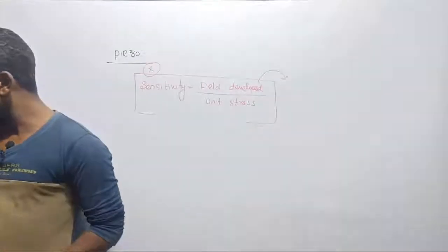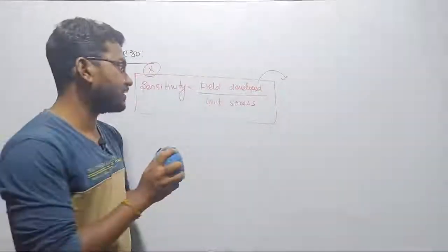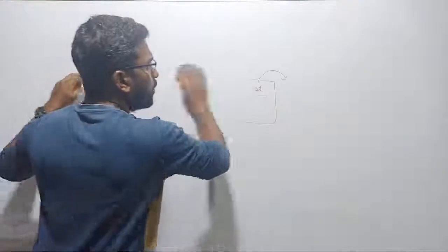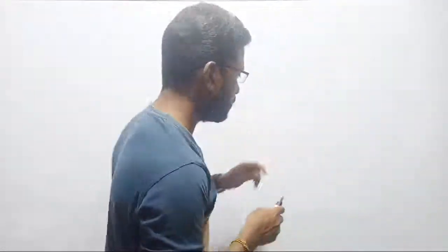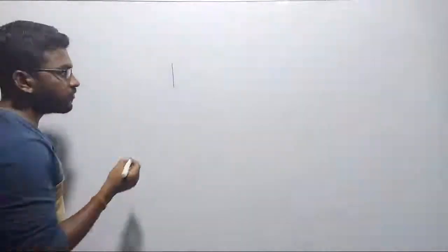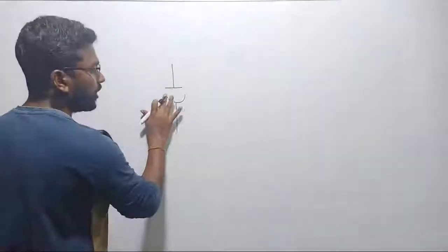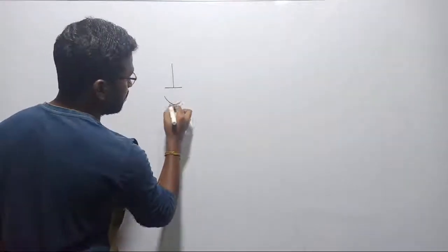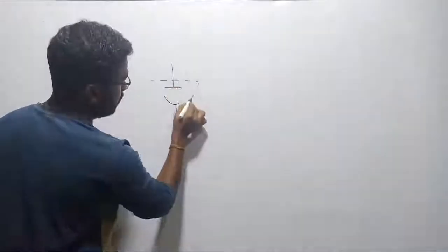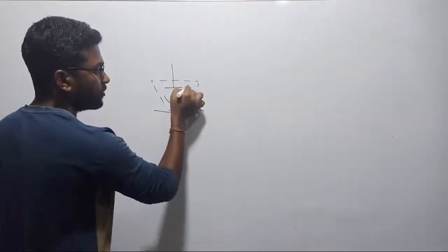And the second thing we saw is photoelectric, right? Photoelectric transducer is very simple. In photoelectric transducer there were no big things to understand. Whenever we are passing light from the outside, there are two plates. We are simply calling it the diode principle. It works under the principle of a diode only, and its layout is a diode only. So this terminal we are calling the cathode, and this is going to be the anode.